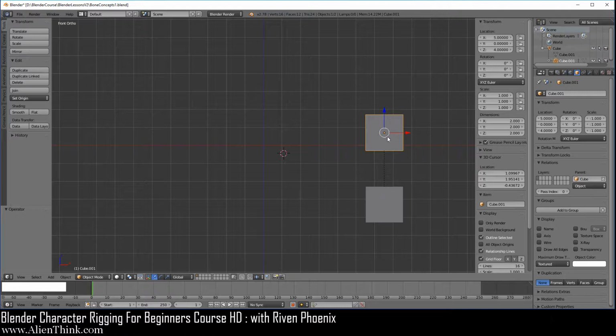Now, when we click on the child and actually move the child to change its distance, it's again doing this based on that imaginary origin over here, right? See how I've moved this object over here? When we click on the X, it's going to go back based on where the original origin point was. Okay, I'm going to do Control Z to undo this.